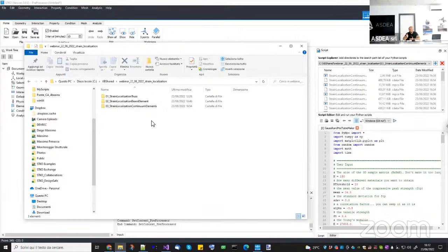And the other problem is the second one that I showed you. The amount of dissipated energy will depend on the finite element size, because as you have seen, since the elements are connected in series, only one of them will dissipate energy, while the other will unload elastically or with a secant matrix or whatever. So only a small portion of the energy will be dissipated by all the elements, but all the other energy up to the complete formation of the crack will be dissipated only by one element. Now imagine that this energy is being dissipated in only one finite element, it means that the total energy dissipated by the system will depend on the finite element size. And this one is the second problem, okay?